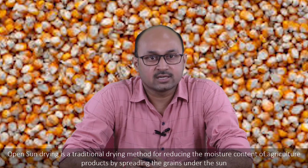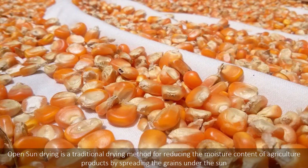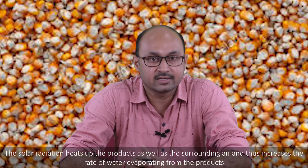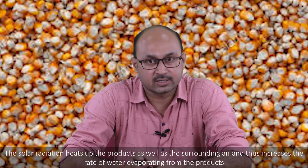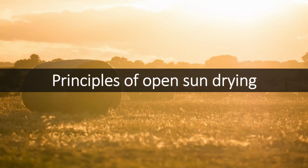Open sun drying is a traditional drying method for reducing the moisture content of agriculture products by spreading the grains under the sun. The solar radiation heats up the product as well as the surrounding air and thus increases the rate of water evaporation from the product, and your product gets dried. Then what is the science behind this open sun drying?